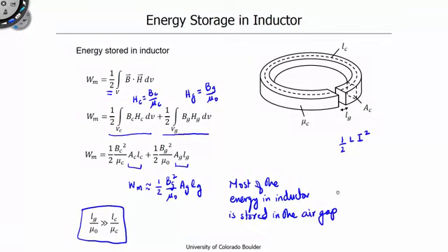This realization supports our earlier determination that the inductance of an inductor with an air gap is really determined by the properties of the air gap rather than the core, since most of the energy is really being stored in the air gap.